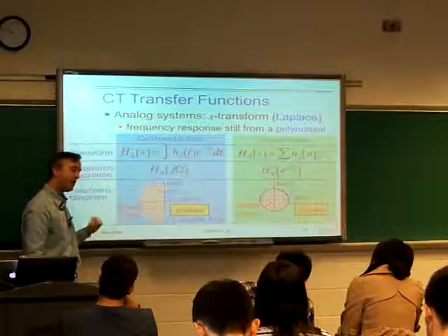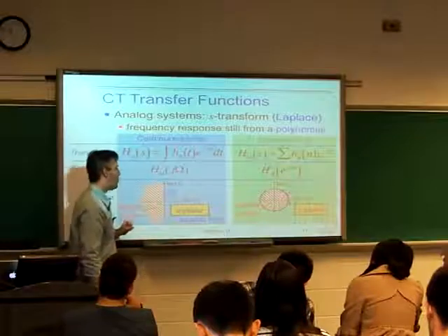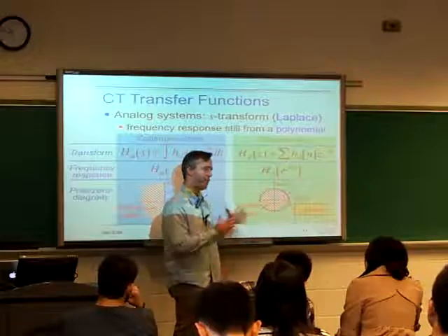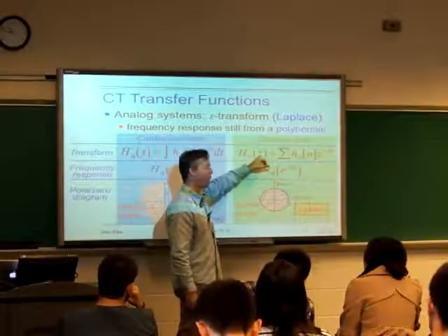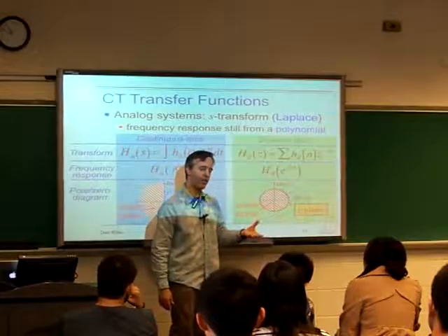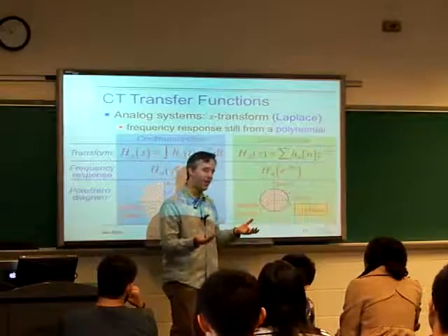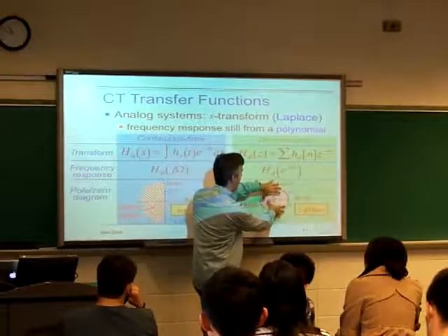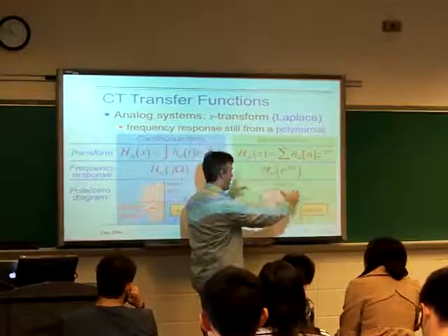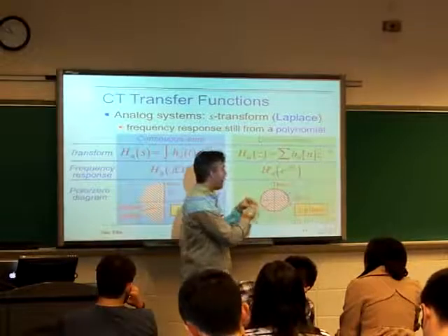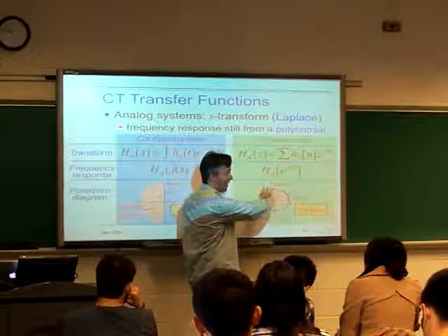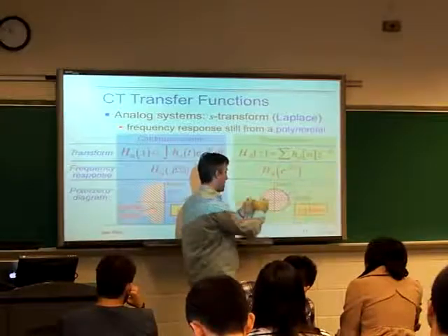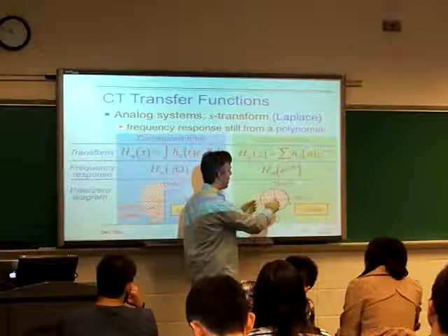One interesting consequence of that is, well, we saw, when we were looking at those transformations, those relationships between different z transforms, if I give you a polynomial in z, you can do a substitution for z. You get a new polynomial out, you just substitute in. And you can think about that as taking the surface and then either twisting or scaling the entire z-plane. Now, if we twist it, we end up with this nice thing with a circle that the frequency response values just get moved to different frequencies. If we scale it, it's not that good because we care about the unit circle.